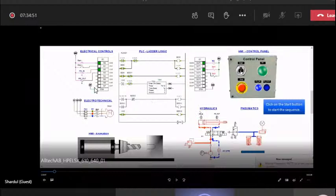So if you observe, if you click on the start button, automatically this particular electrical supply will start, this button will start, and it will give a signal to the input card of the PLC. Now we have an entire ladder logic written here. We also have the timer, as in till what time it should drill and then come back. And also if you observe here in the hydraulic circuit, you have the electrical motor.